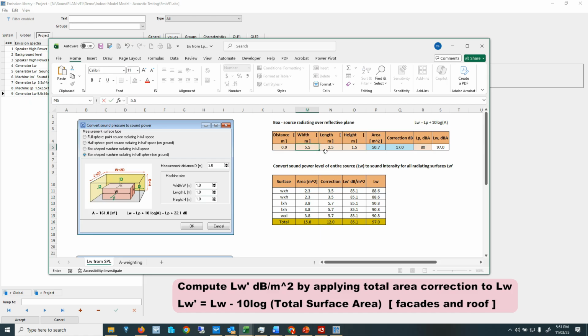Now in this case I have a second table that shows me the different surfaces. I'll put in the general dimension. So here we have 22, two surfaces with 56, 77, and the total surface area is 233 square meters versus 341 square meters where it was 3 feet out from the cube. With this surface area we can assign the intensity level. So the intensity of each of the surfaces is 81.7.